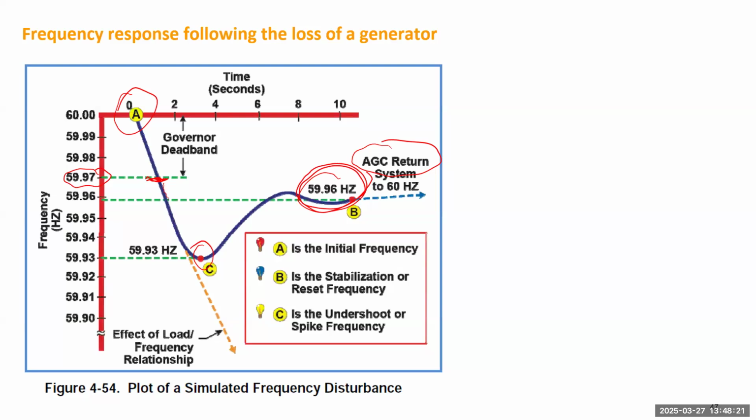They either have no inertia, or their inertia is not directly affecting the grid. Like a solar farm, they don't have inertia, they don't have a rotating part. Wind farms have inertia, but it is connected through power electronics, so you don't really see that much inertia.